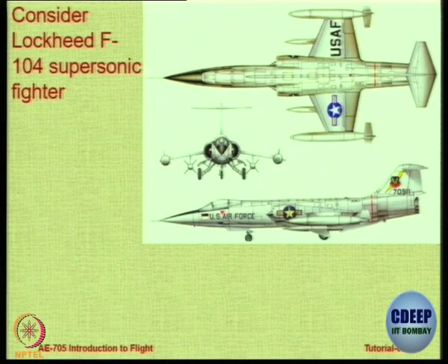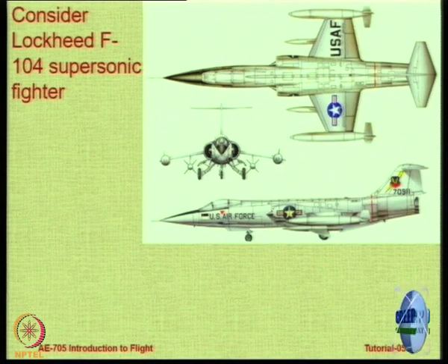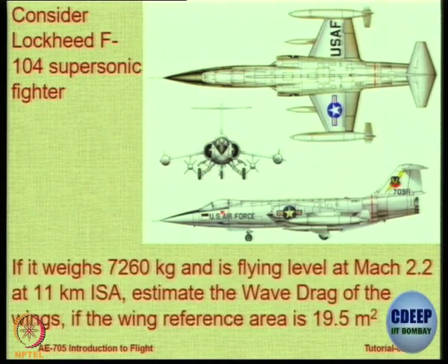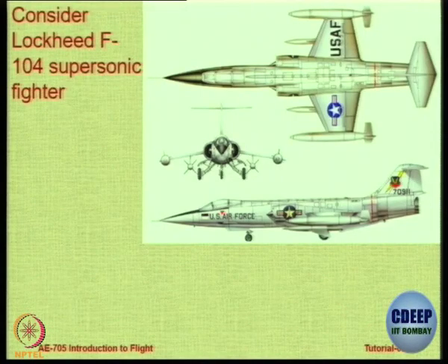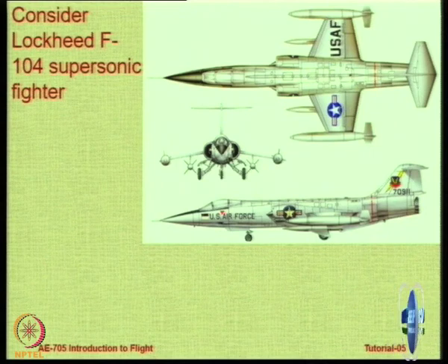Not just the leading edge, not the trailing edge, but at the quarter chord. So the quarter chord sweep is not there. So this is a straight wing with taper. It has taper, but it doesn't have sweep.